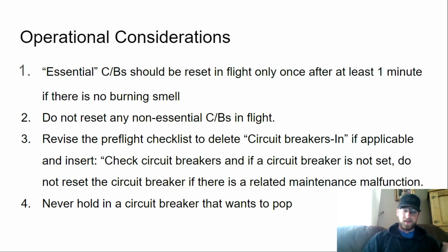Some operational considerations. In 2009, the FAA came out with a special airworthiness information bulletin, and in it they outlined some suggestions with regard to circuit breaker operation. Essential circuit breakers should be reset in flight only once and after at least 1 minute if there is no remaining smoke or burning smell and the affected system and equipment is needed for the operational environment. So the FAA is saying, this is the only time that we should reset a circuit breaker. The FAA also advises do not reset any non-essential circuit breakers in flight. So if you don't need it to safely execute that flight, don't reset it.